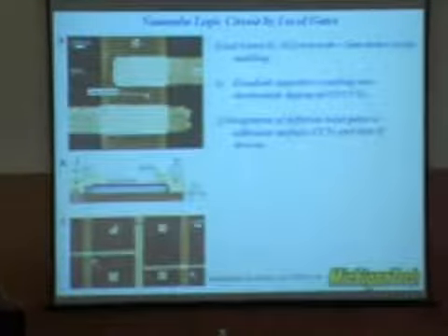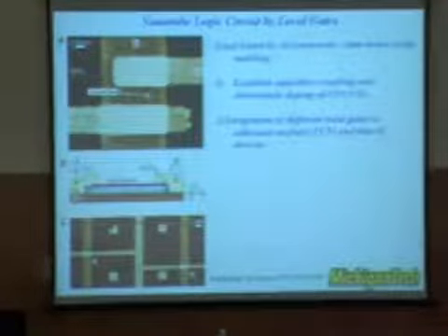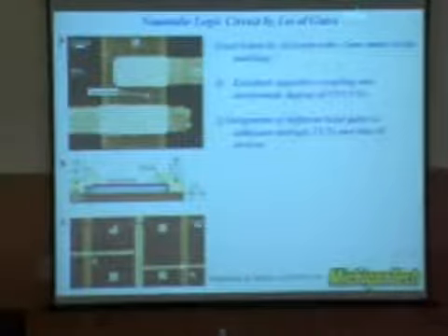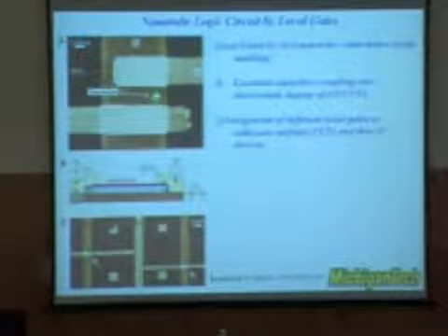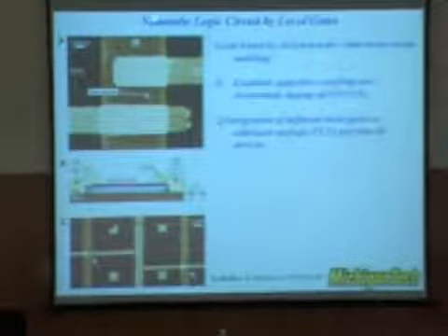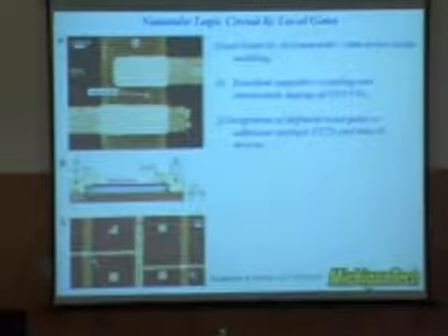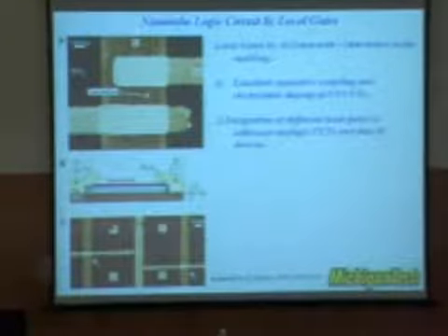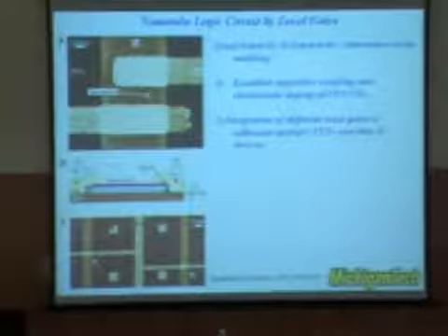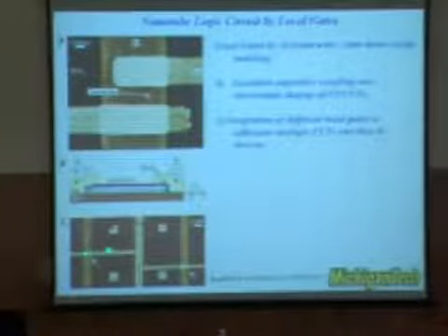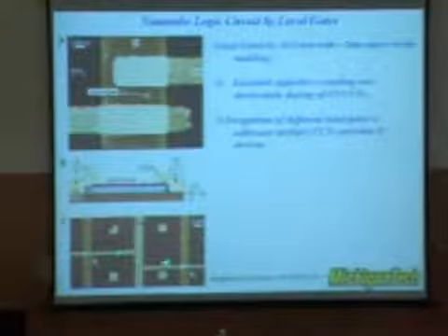And actually, a few months later, a paper in Science progressed much further from the idea that I showed you just now. In this case, it is using a local gate. The so-called local gate means each conduction channel here has its own gate electrode. You can see here that you have an aluminum line, and each of these aluminum lines will have a very thin layer, about 2 nanometers thick, of native oxide. They will enable the switching of the gate of your transistor. And you will have a piece of carbon nanotube laying across these 2 electrodes, which are the source and drain here.